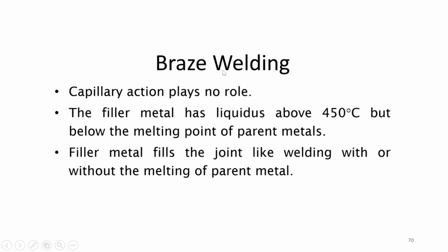In braze welding, capillary action plays no role and the filler metal has a liquidus above 450 degrees Celsius but below the melting point of the parent metals. The filler metal fills the joint like welding, with or without melting of the parent metal.